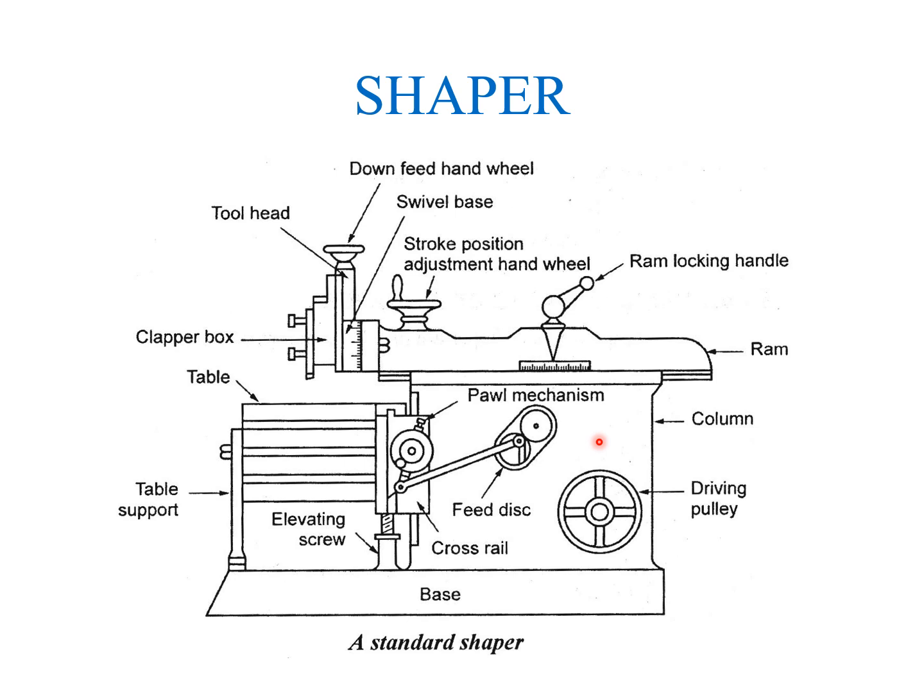Next, stroke adjuster. It is attached below the table. It is used to control the stroke length, which further controls the ram movement. Then table supports. These are attached to the front side of the table and used to support the weight of the table during working.